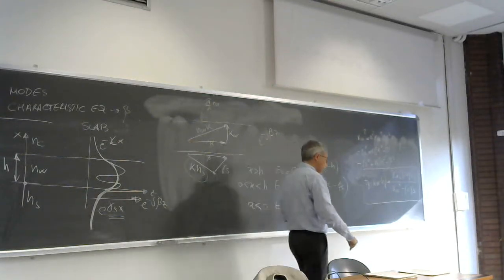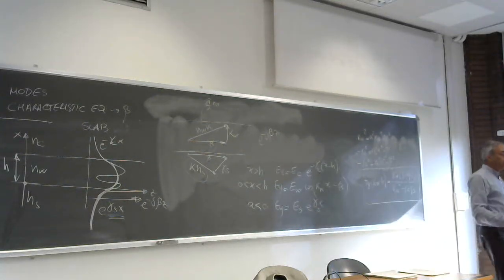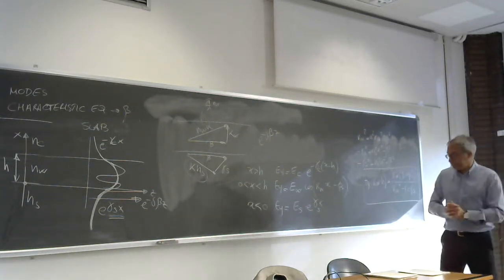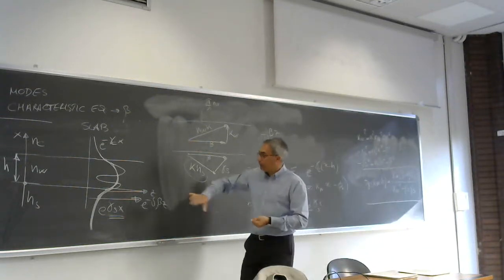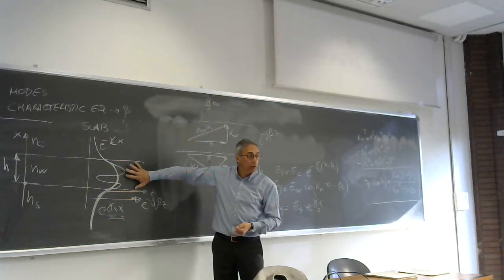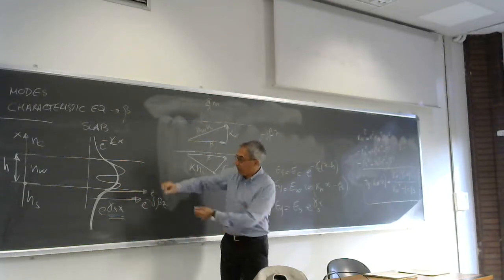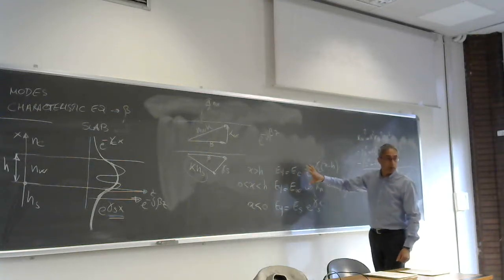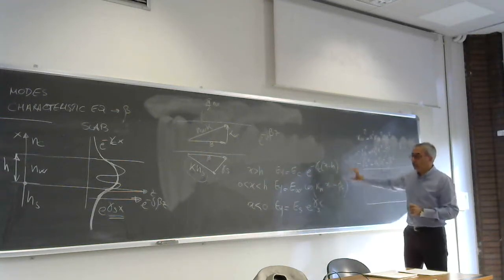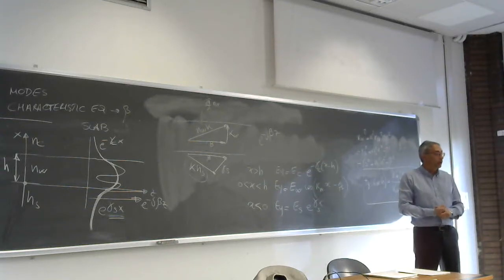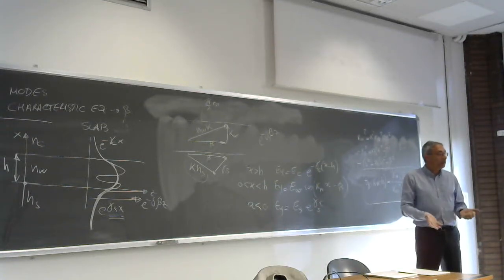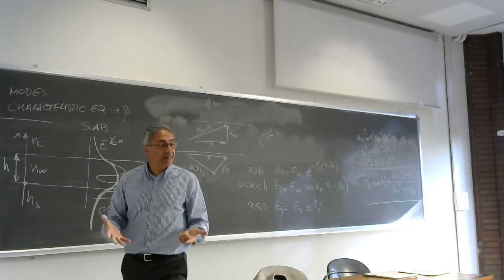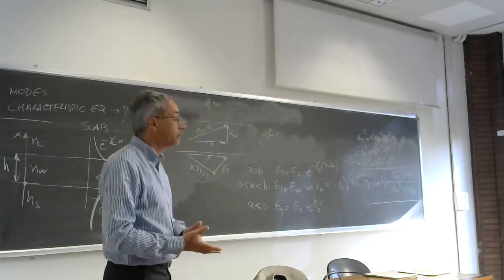If there is no propagation in a direction perpendicular to the waveguide, it means that the energy is confined around the core. It does not lose energy, energy does not go away, and continues to be localized around the core along the propagation, along z, along the waveguide. The shape remains the same. It is a mode, with all the characteristics of the mode that we discussed yesterday.